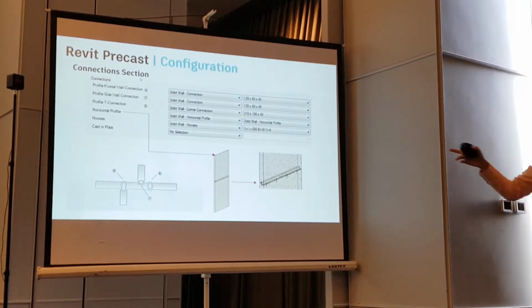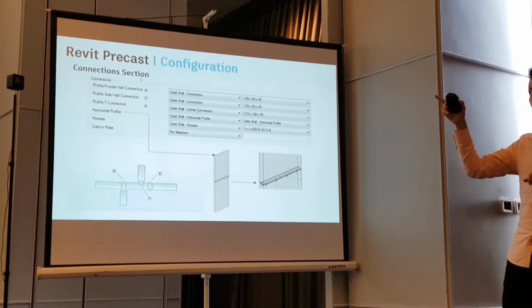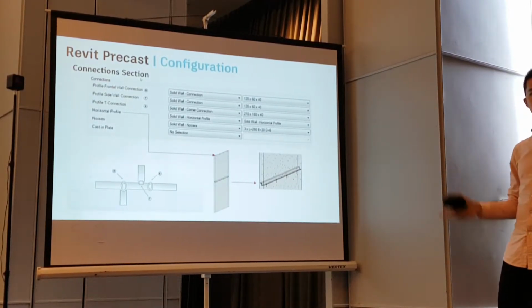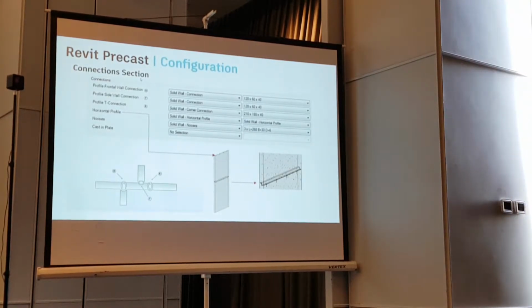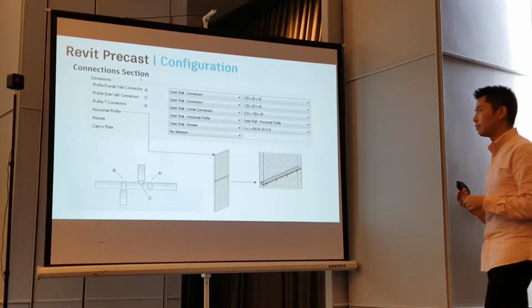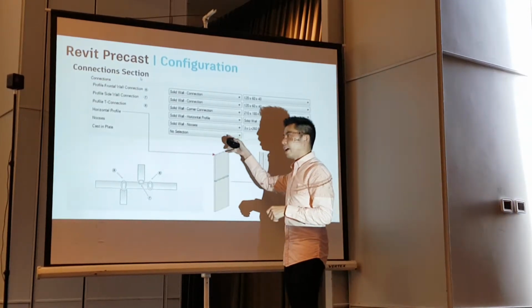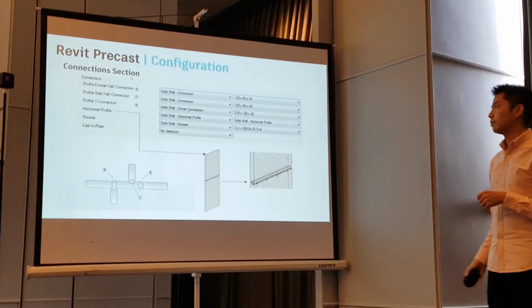Again, go to ProgramData/Autodesk/Structural Precast for Revit and go into the profile folder. All the profiles are in there. If you want to create a new one, create it and put it into that folder. Noses, same thing as well, and custom plates. All the settings are in there.